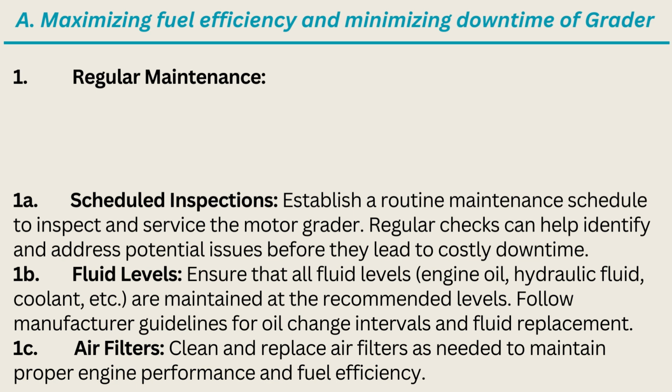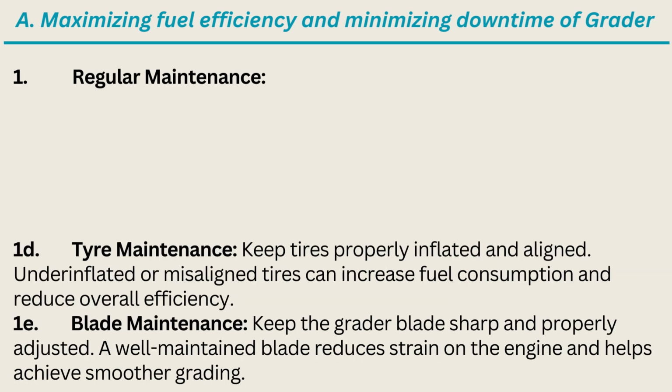1B. Fluid levels. Ensure that all fluid levels, engine oil, hydraulic fluid, coolant, etc., are maintained at the recommended levels. Follow manufacturer guidelines for oil change intervals and fluid replacement. 1C. Air filters. Clean and replace air filters as needed to maintain proper engine performance and fuel efficiency.